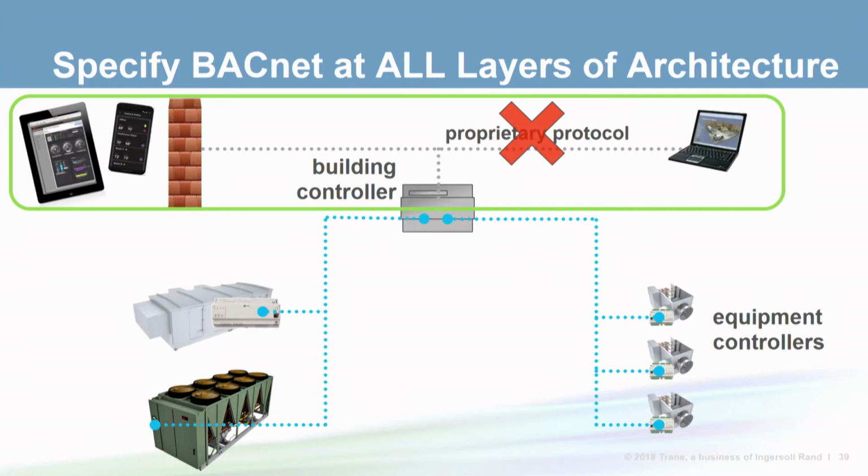Although that may seem obvious, I mention this because there are control vendors today that promote a proprietary communications protocol as an open communication solution. The problem is the protocol is only available with devices they manufacture, which is by definition proprietary. The devices they make support both BACnet and their proprietary protocol.